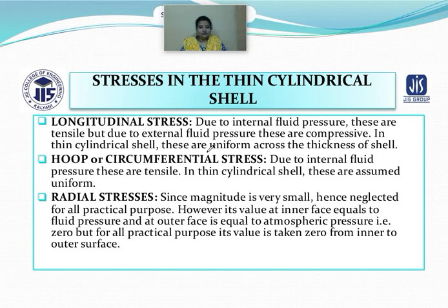So if you see this longitudinal stress, it is due to some internal fluid pressure. These are tensile, but due to external fluid pressure, these are compressive. If your thin cylinder is completely filled with some fluid, then obviously this fluid will exert some pressure.